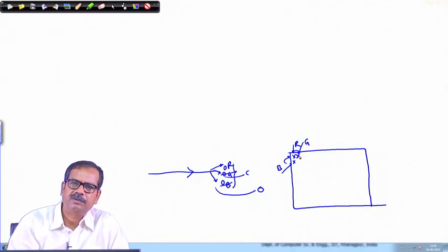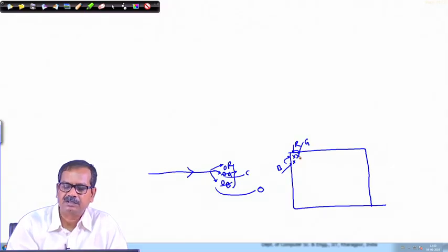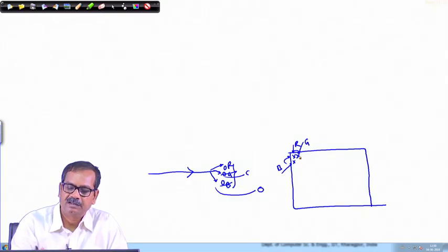This is a very crude way of estimating the colors, that is, assigning full color information to each pixel. As you can see, it is very crude, because I am simply transferring the values of missing components to the neighboring pixels by considering the spatial correlation of the spectral channels.